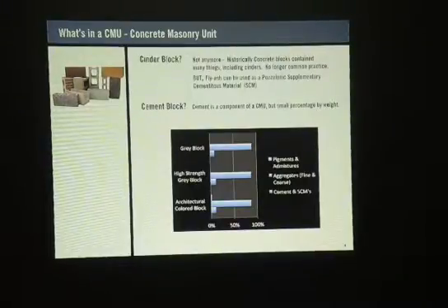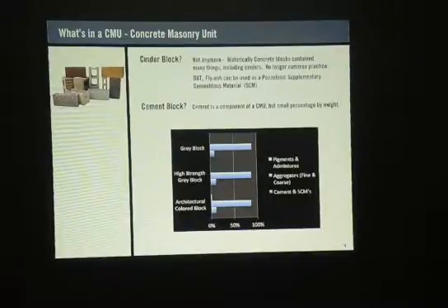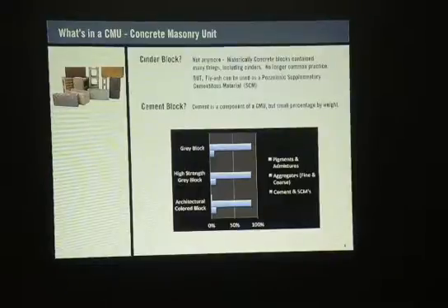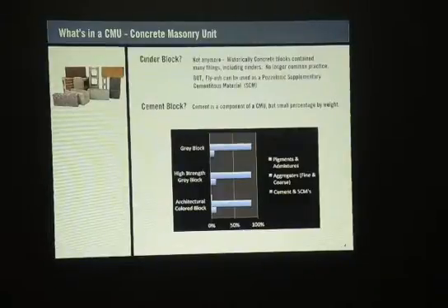But if we went with high strength block, let's say we're doing a hospital, a school, a detention center, a prison, all of these are very practical building applications where they're not retaining walls or perimeter site walls. The PSI compressive strength is 3,750 minimum for high strength block. So like I said, it was almost double.